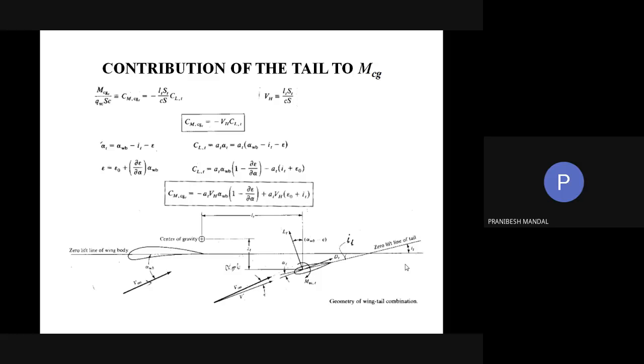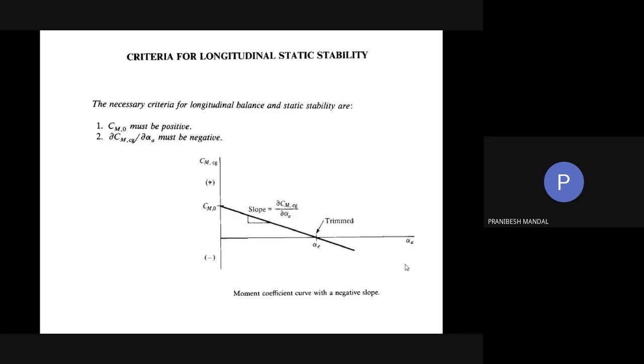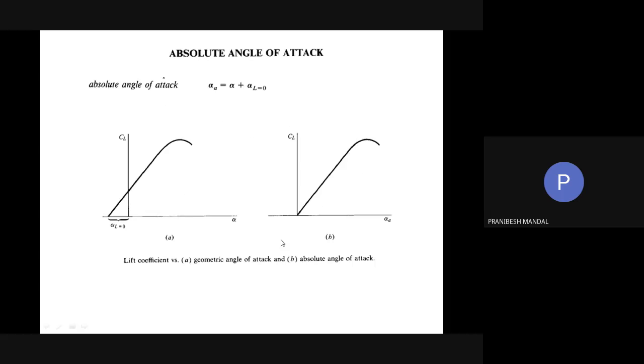Epsilon I don't know. That is the downwash angle. I really do not know epsilon, right? No, sir. So for epsilon again, we need to go back to the wind tunnel data. And as we have no particular data about epsilon, we have found epsilon with respect to alpha, and I may assure you the curve is exactly similar to this particular curve.